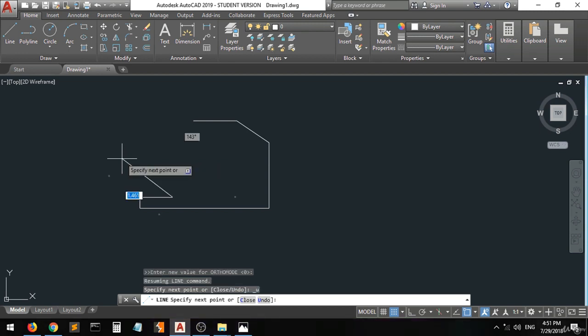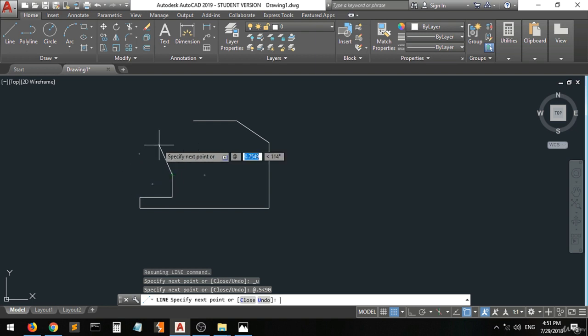You can just do Control Z at, let's do it wrong, 0.5 in the angle of 90, okay. We'll do it what? 0.75 but in the right angle, right? So we'll do it at 0.75. We don't have to enter the minus because when you enter the minus, let's show you how it works. Minus 0.75 in the angle of 180, enter.